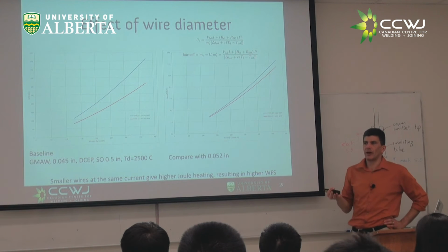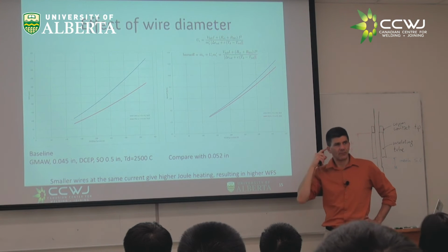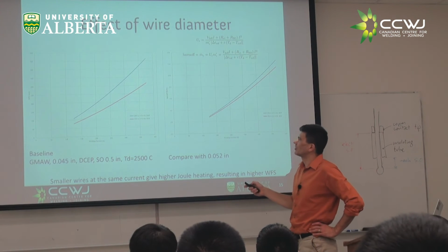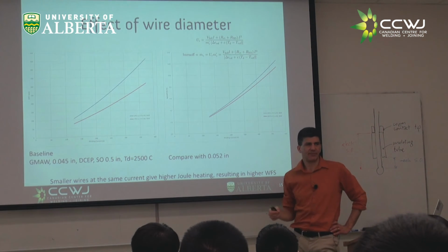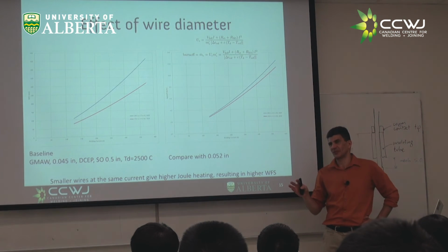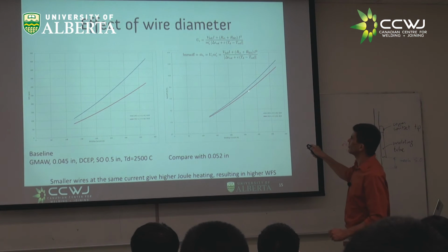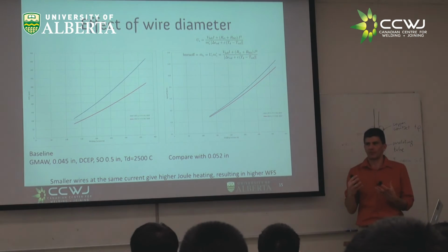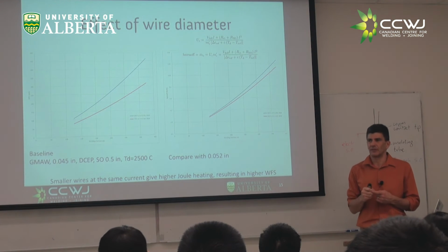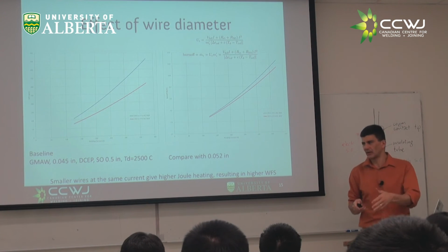So you can get to choose either wire, and you'd be fine. I don't think your company is going to go bankrupt because of this. But you start to understand things, right? If somebody tells you, well, you should use 045 because the wire feed speed is so much faster. Yeah, wait a second. Kind of true, but not completely true, because it moves faster, but it's thinner. But there is a little bit of an advantage. Yes, that is true, a little bit. But you're aware of that. And with this formula you have here, you can calculate this yourselves, and with the values that you have tabulated that I gave you. And you can, right there, settle these types of arguments.